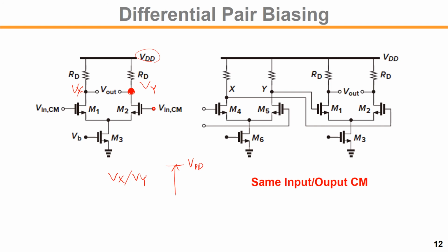As you can see, the maximum input voltage here is VDD, so the output of one stage goes into the input of the other stage. So the maximum input voltage is also VDD. If that is VDD, the drain voltage will be minimum. In that case, how low can it go to ensure that M2 is in saturation?